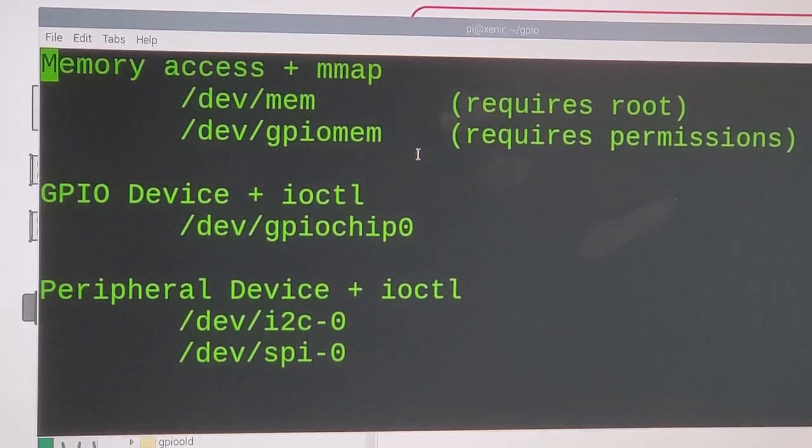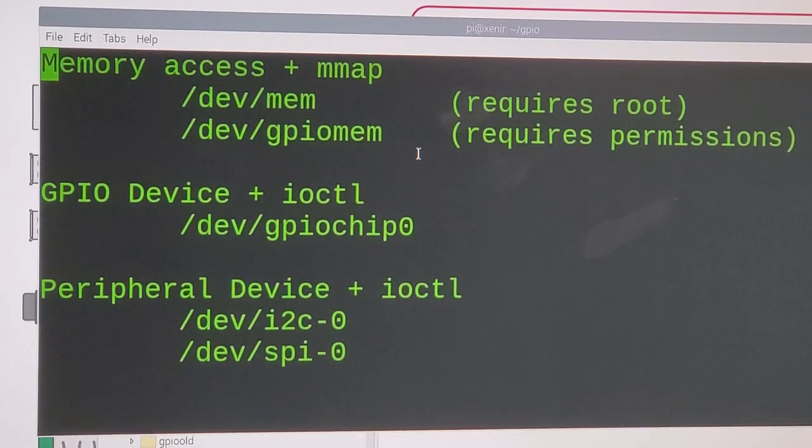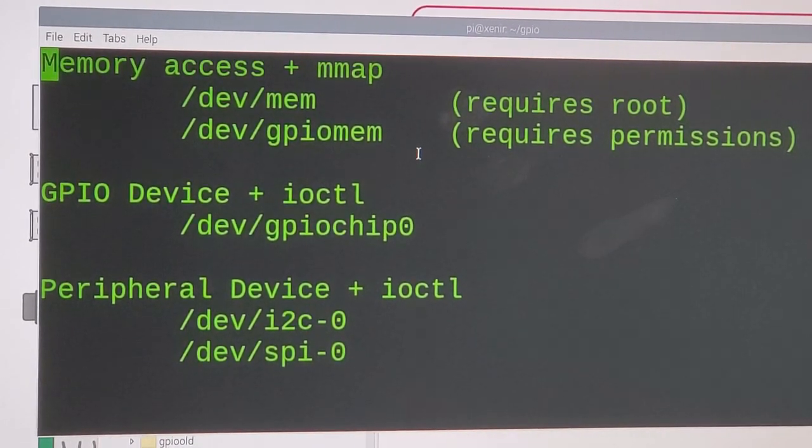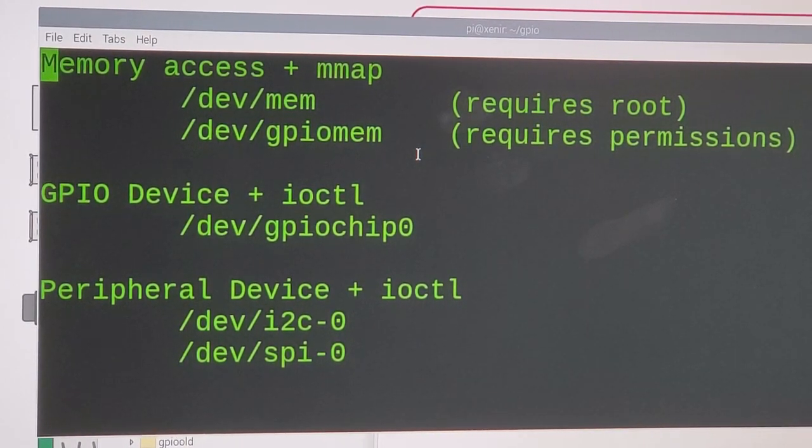Now one of the primary differences from bare metal programming is you don't have any interrupt processing, so you can't register an interrupt on a button press and then get a callback when that button gets pressed. Now, there are techniques to do that, which I'll be walking through some of, but that's one of the primary differences. Also, you can't use DMA here. So that does present a bit of a challenge if I wanted to do some I2S programming down the track. And obviously, at that point, I'd probably have to write some kind of kernel driver or something like that to access the I2C and do DMA or interrupt programming.